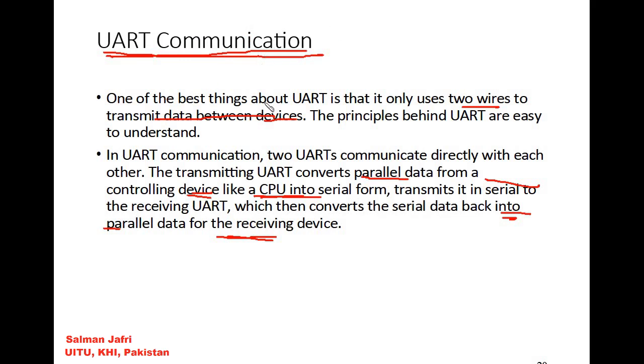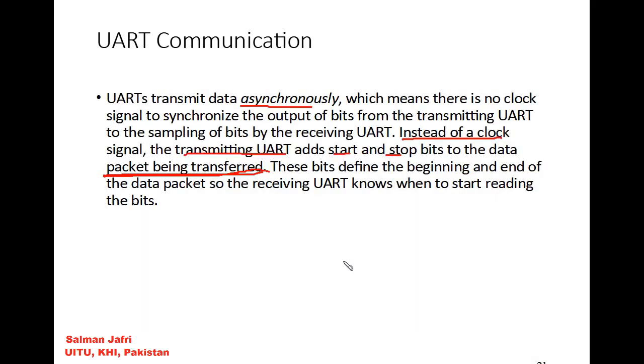So what is the best thing about the UART? It requires only 2 wires to transmit data between the devices. And for that matter, USB is also a serial protocol, so it requires only 2 wires, data plus and data minus. In UART communication, 2 UARTs communicate directly with each other. The transmitting UART converts parallel data from a controlling device like the CPU to serial form, and transmits the serial data to the receiving UART, which then converts the serial data back into parallel data for the receiving device. Like I have discussed before, this is similar.